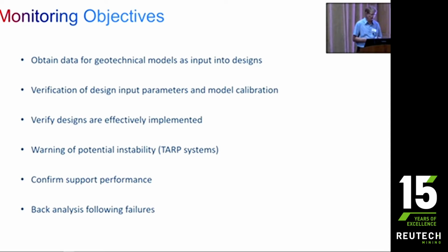So, general monitoring objectives. Why do we monitor? Firstly, it's to obtain data to inform our geotechnical models, and we use that as input into our designs. Once we start mining, it's to verify that the rock mass is behaving like we predicted, or if it's not, to change our input parameters and redesign.